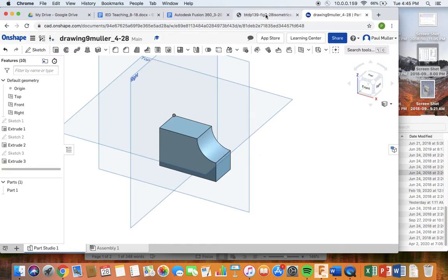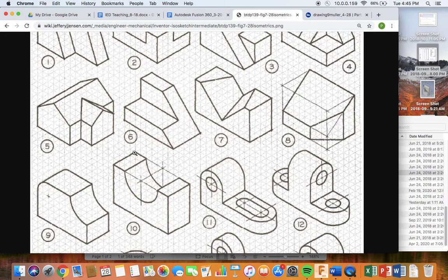All right, there is one last feature of this drawing, and that is a filleted corner. That is a smooth or curved corner. So let's add that in. Now you might say, what's the radius of this fillet? Well, it's hard to tell, but it looks almost like the radius is 0.25 or 1 square. Do you notice that one end of this arc goes to that corner of the grid square, and the other end of the curve goes to this corner of this grid square? So that looks like a 0.25 inch fillet.